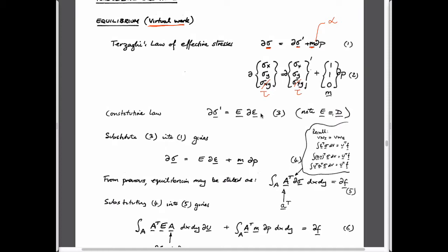So now that we know what our effective stress law is, we could go back to what I just said previously, and that is that when we look at relating strains to stresses through our constitutive matrix, so this is the D matrix that we've referred to before, then it's not total stresses that are defined by this, but effective stresses.